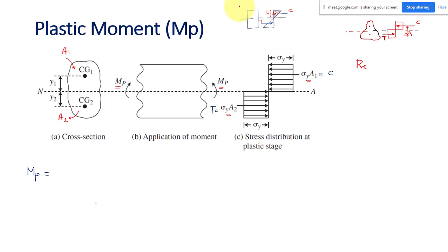So again you have to see, this is the first case. I have a regular geometry and the stress is varying. I have an uneven loading. So then the resultant compressive force will be acting at the CG of your stress block, because finally it is not the stress block or geometry. Finally what you have to see is the force only, the point of action of the resultant force. Okay, and here I have uneven geometry and I have a constant loading.